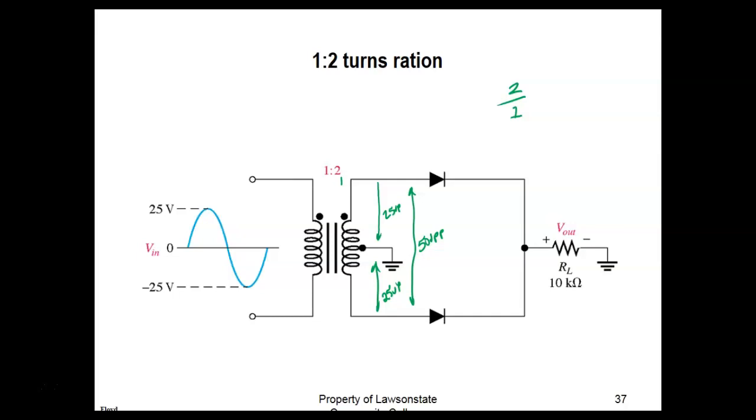So my output voltage, so let's take that. So this is RMS, and since it's a center tap transformer, we're only using one half of it. So the biggest problem I have in this class is people want to use that 50 volts right there, and not seeing the center tap and understanding that we only get one half. So let's try that. So this would be 25 volts. This would be 25 volts peak, right? No, RMS. Ooh. So our formula won't work because the formula depends on it being RMS.